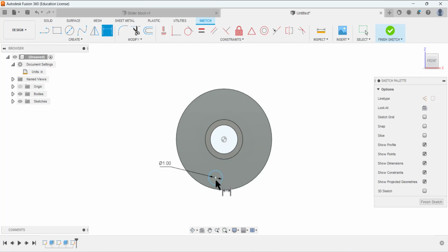And now we want to make sure this center point and this center point must have a common line, meaning this point must be facing this origin. So select the horizontal vertical, select this center and this center. So these 2 points are on the same vertical line. If we have a line from this point to this point, the line is also a vertical line. Okay, select, and now we have to define a dimension from this point to this point. This dimension in the drawing is given as 5, a diameter dimension. We have to divide it by 2, so 5 divided by 2.